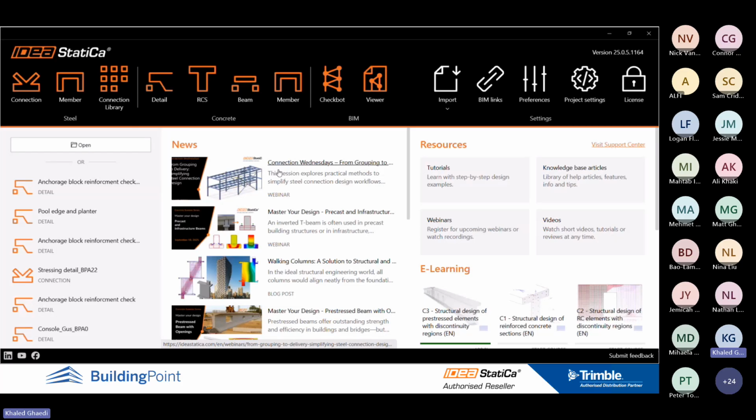Okay, so after putting in the loads, you need to define the load combination. So you can go to load combination. So here I have one dead load, which is self-weight, and also live load. So here I want to just consider a combination for serviceability. So I will name it as service. And then let's go for short term.